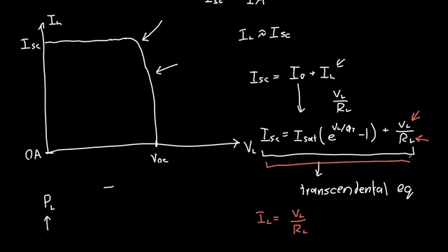Well, we want to maximize both the current and the voltage, or we want to maximize their product. So we want to get as much current as we can without decreasing the voltage across our load. We want to be operating somewhere about here, or maybe here, just as the current starts to decrease and our voltage continues to increase. This operating point will give us the maximum power.